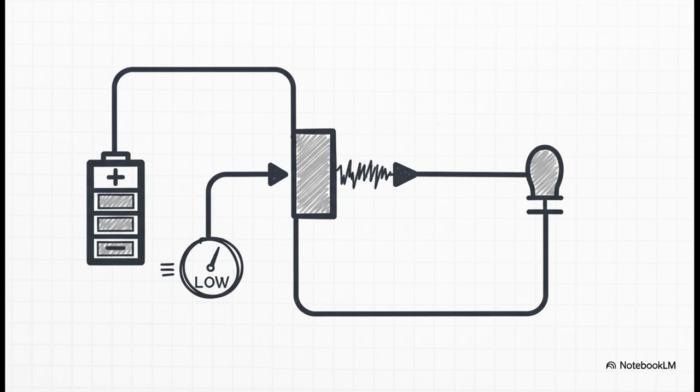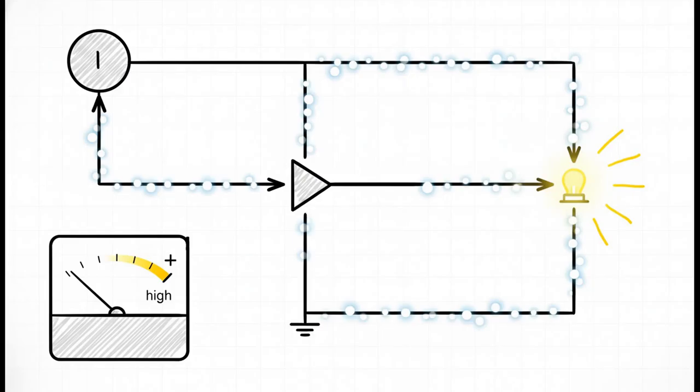We're applying a voltage to the base. So if that voltage is less than our magic number, let's say 0.5 volts, the transistor just sits there. It's non-conductive. It's basically an open switch, so no current can flow, and our little LED stays off. But the very moment we nudge that base voltage up to 0.7 volts or just a little bit more, the transistor flips. It instantly becomes conductive. It's like the switch is now closed. Current starts flowing through and, boom, the LED turns on. It's a perfect, simple, reliable electronic switch.